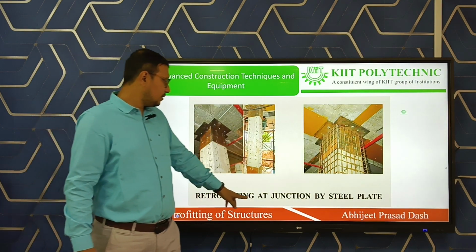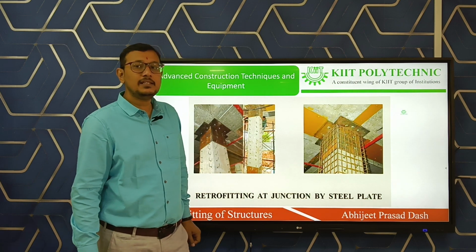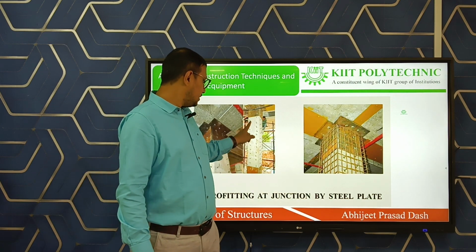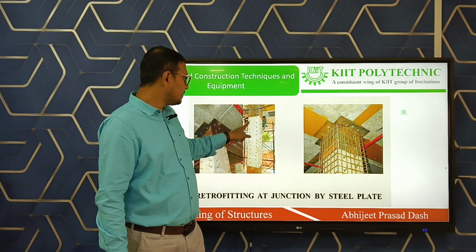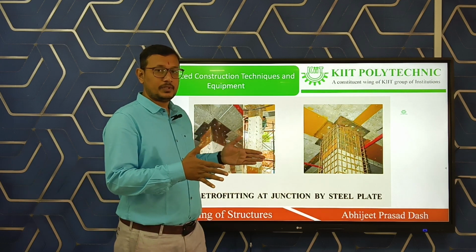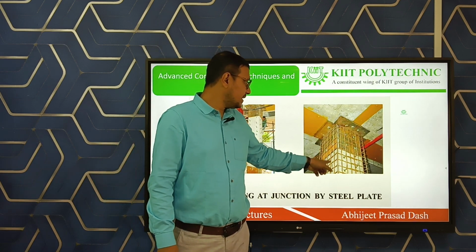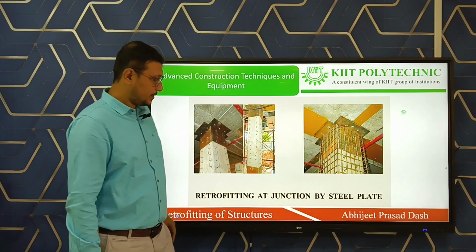You see retrofitting at a junction by steel plate. This is one where we are providing steel plates and jacketing here by providing reinforcement.